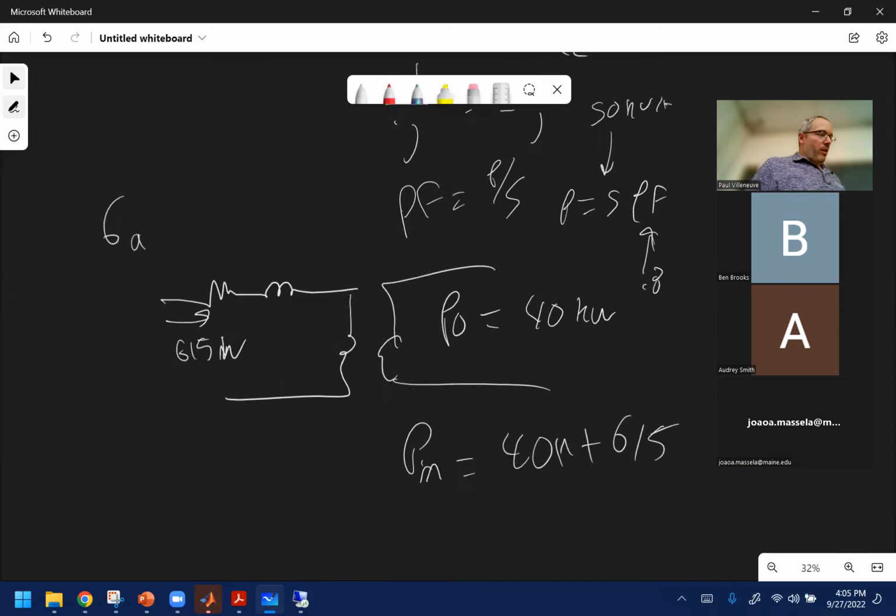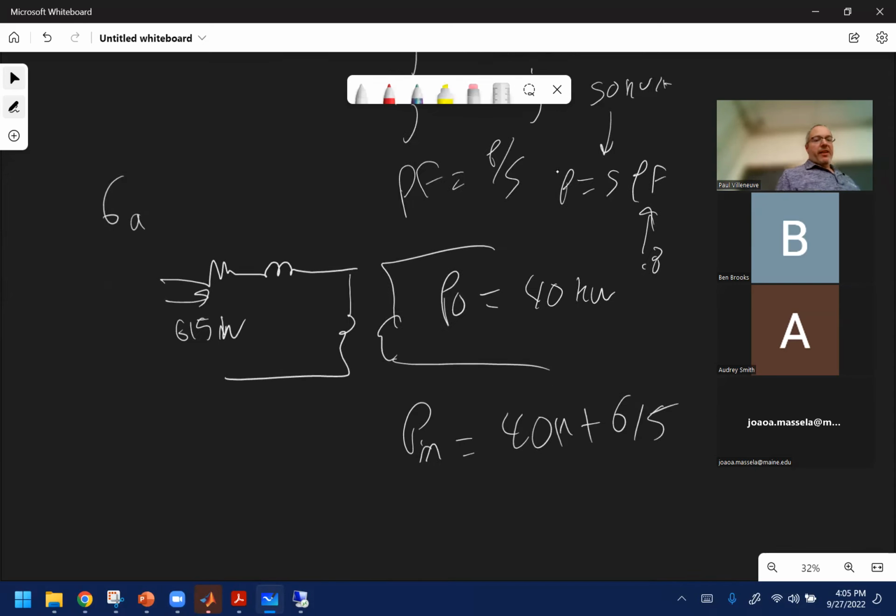And for this last one, all I wanted to know was the phasor diagram. So you pick your voltage as your reference, and then your current is here. Calculate what the current is on the low voltage winding. And this here is the inverse cosine of 0.8. That's it. That was a test.